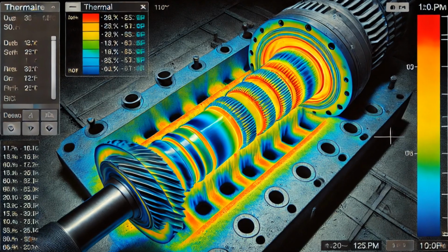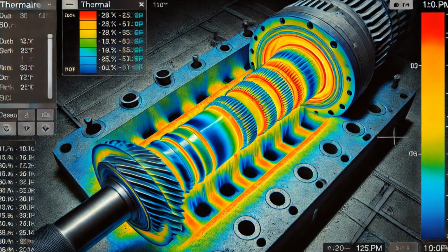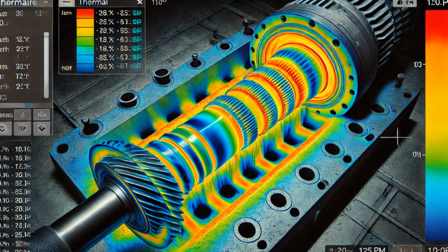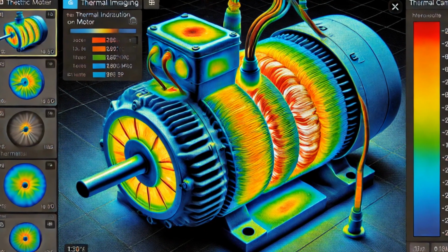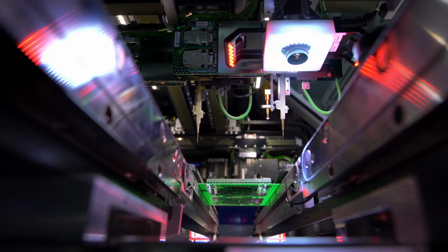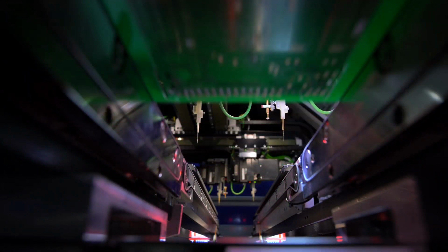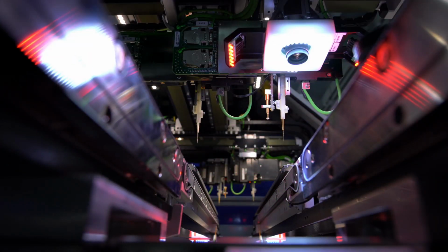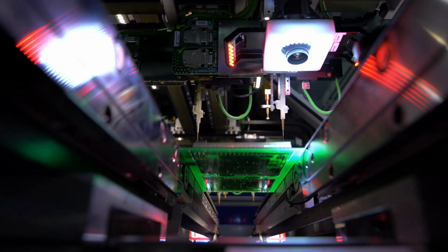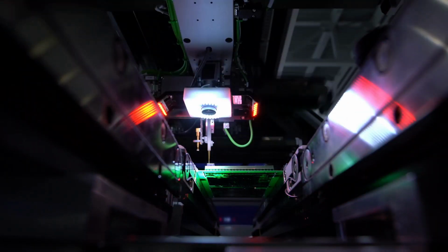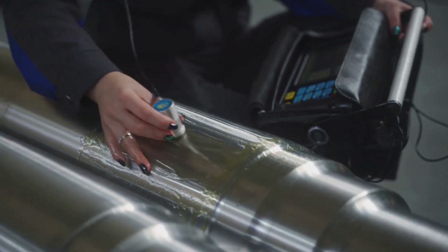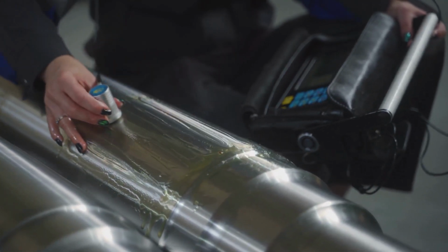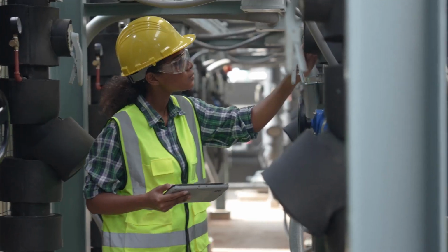By analyzing thermal imaging data over time, patterns of gradual heat buildup, emerging hotspots, or abnormal temperature fluctuations can be detected before they lead to equipment failure. Trending thermal data helps identify progressive wear, misalignment, electrical resistance, or cooling inefficiencies, allowing maintenance teams to predict failures, schedule proactive repairs, and optimize system performance. After reviewing trends for the component in question, it is crucial to cross-check findings using complementary diagnostic methods.